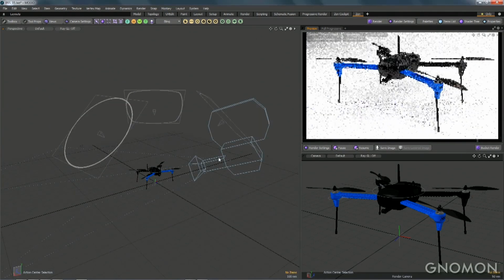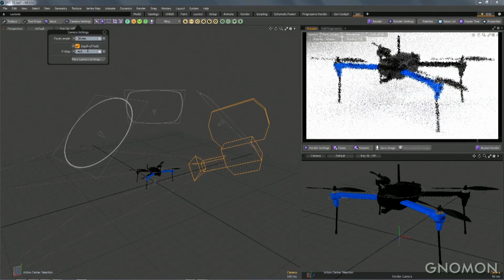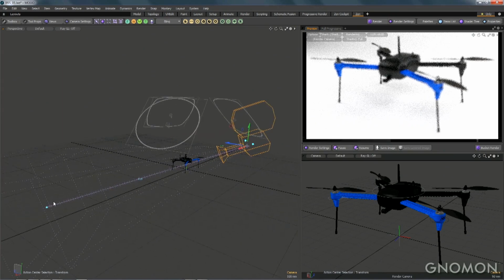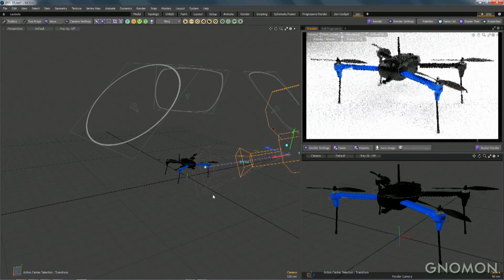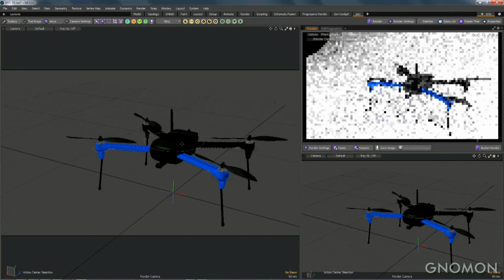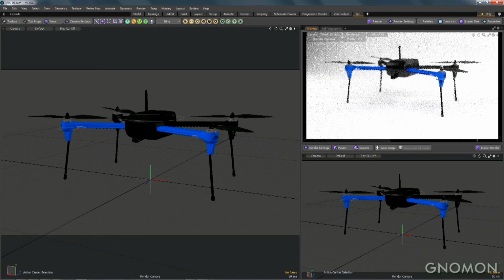So let's talk about something a little different here. I've got a camera. And I'm going to turn on depth of field. And as you know, with Modo cameras, you can set the depth of field really easily. Just drag a little node around. But it is a manual adjustment, and that stays static. That focal distance doesn't change, even if I move my camera around. So as soon as you move the camera, everything is out of focus.